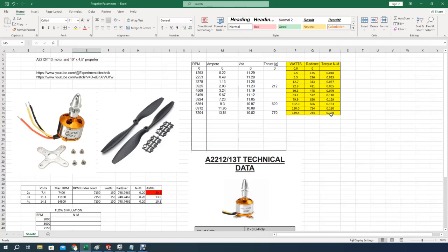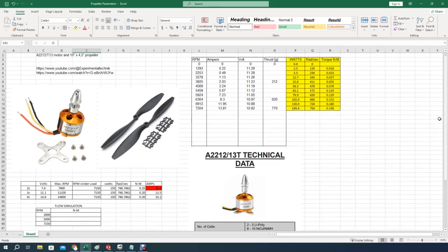So that's the idea, because I'm not going to be using this blade. I'm going to be using different blades or different propellers. So at the end, what is important to do comparison is never to exceed the 0.2 torque on this motor. And with that, then you can calculate anything else that you need, like for example, thrust, and that's on SolidWorks using flow simulation. So to make a long story short, now that I know that 0.2 is the maximum torque